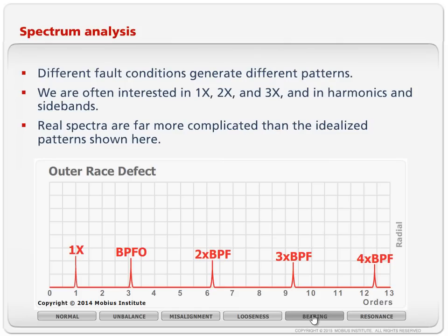Sidebands, what would that tell me? Lots of peaks, high amplitude, low amplitude, all these patterns should tell you what must be happening inside the machine in order to create those patterns. And that, in my opinion, is how you become a good vibration analyst.